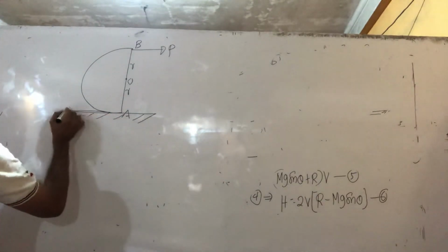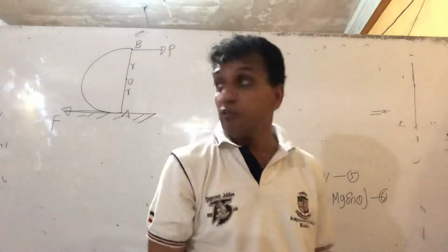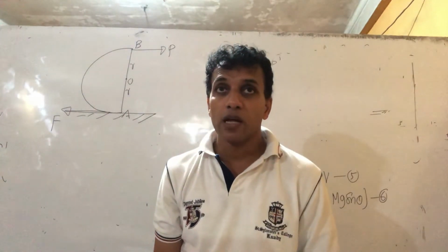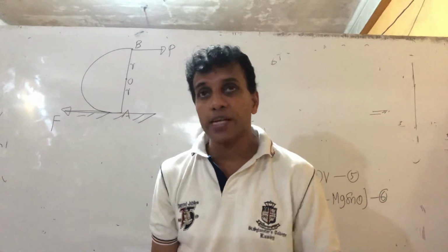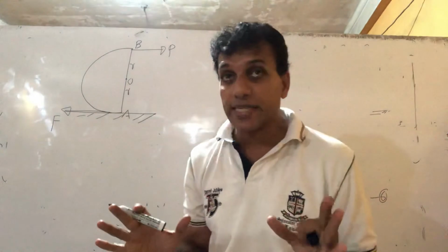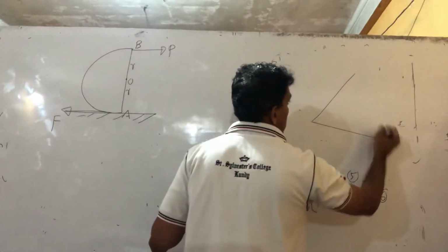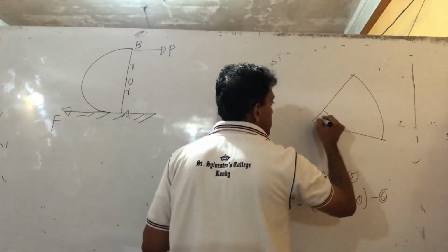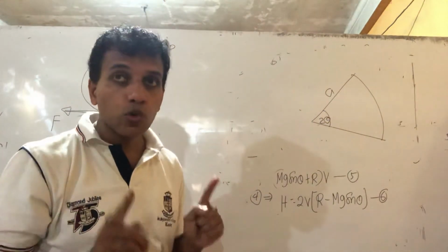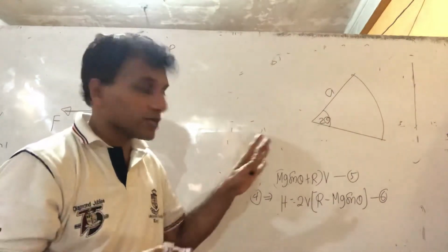Therefore here, what is the friction force? F here, right? So what is the other force? The weight of the semicircle lamina. You have already completed the center of gravity lesson. The center of gravity of a lamina that subtends 2 theta at the center, radius A, is 2/3 A sine theta over theta. I hope you know that. Otherwise, study the note on that.